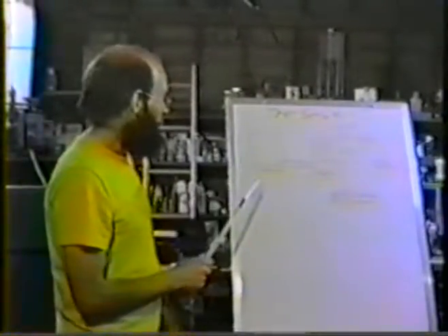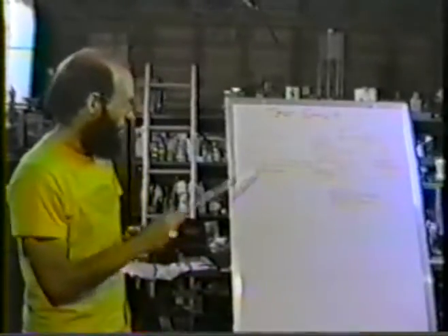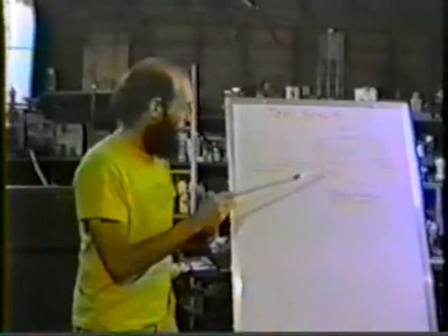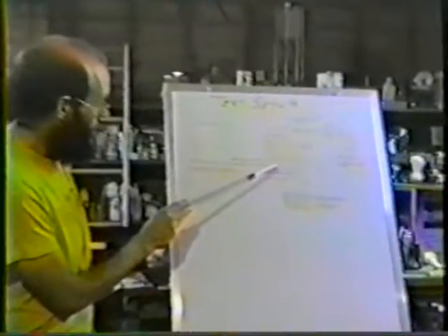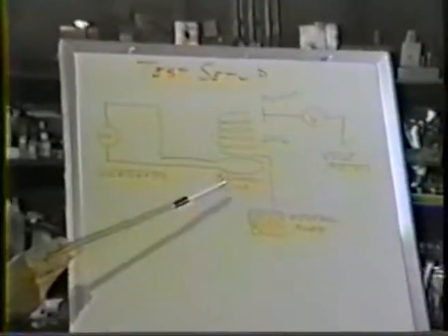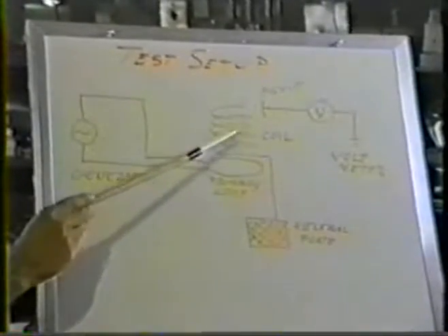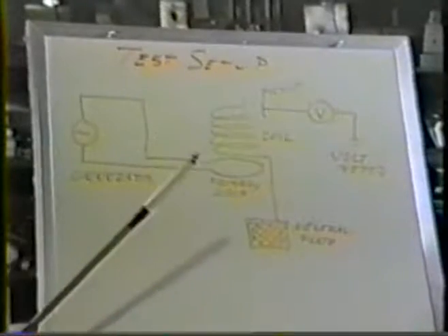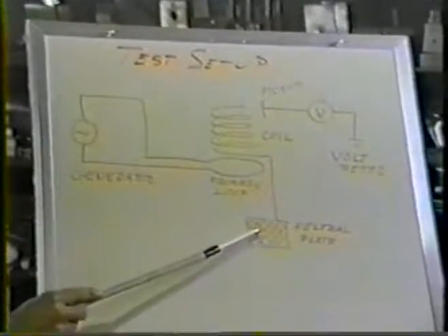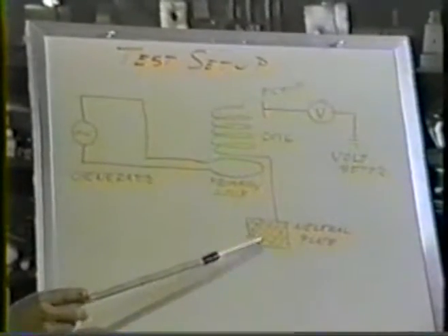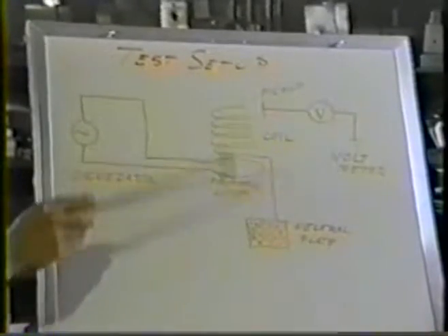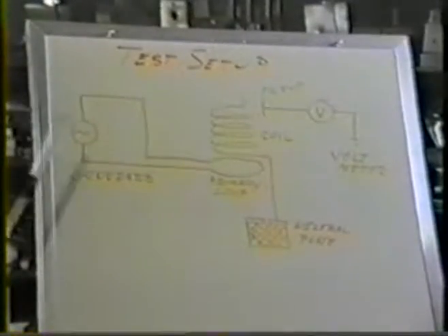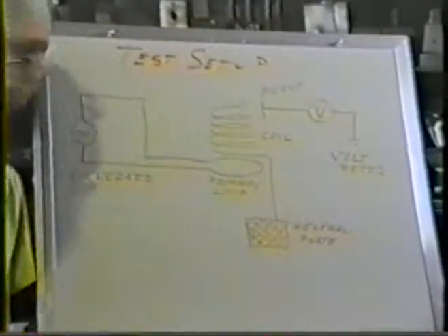Okay, now we have our longitudinal wave test setup. Again, we have the same generator. This time our transformer couples the generator energy to the first turn of the coil, which is wound of fairly fine wire. And then we have a capacitive probe pickup to measure the voltage rise at the end of this coil. And at the neutral end of the coil, we have a large capacitance plate to produce our impedance dissimilarities, so we end up with a quarter wavelength rather than a half wavelength resonance on this coil. Now we'll look at our test setup again here.